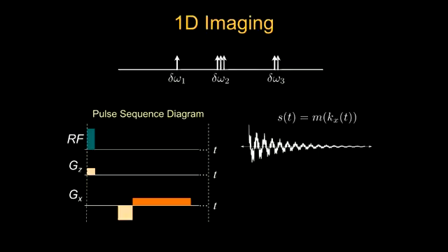So if you collect all the signal and apply the 1D Fourier transform, you can decompose the signal strength. That's the theory behind MRI: you create the signal, assign a different frequency at each location, record the signal, then apply the Fourier transform and decode the strength of that signal.